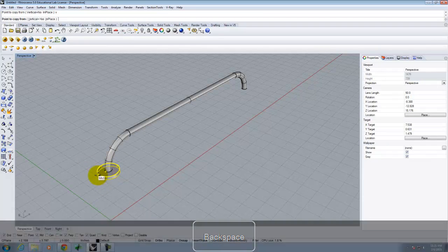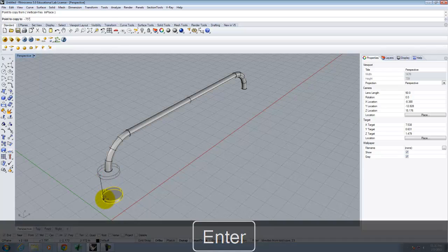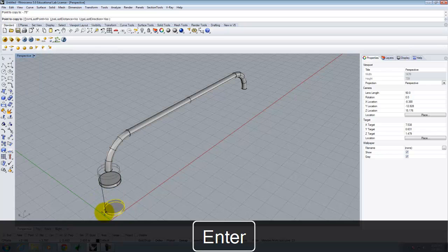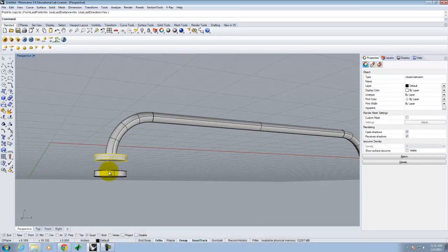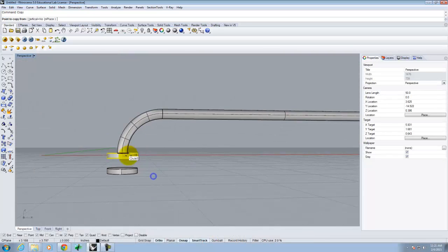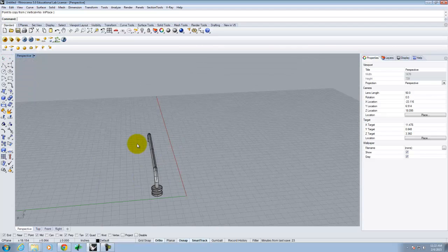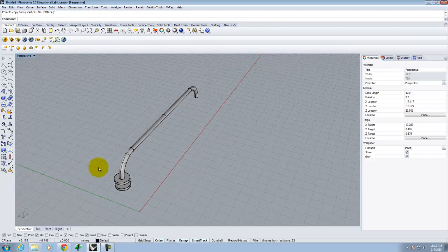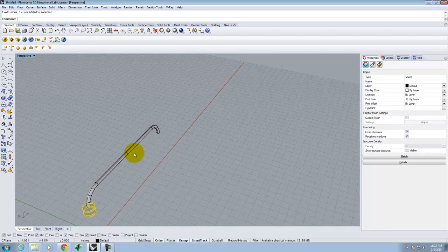We can do it from the center again, or we can do it from one of the sides. Negative 0.75 inches, which is going to leave me with a ½ inch gap for my sheet of glass. Okay? So I have a button on top and a button on bottom with a little ½ inch in between. So the good news is I can use mirror to my advantage here. So I'll select both of those buttons and then use transform mirror.